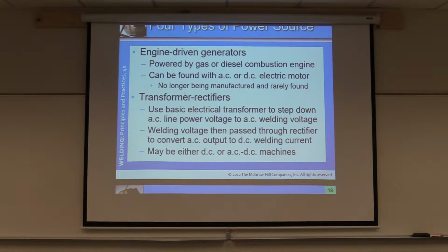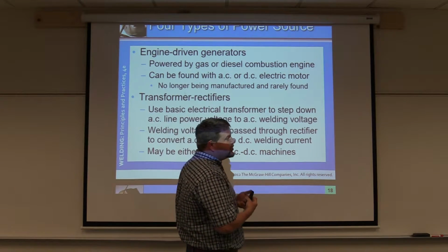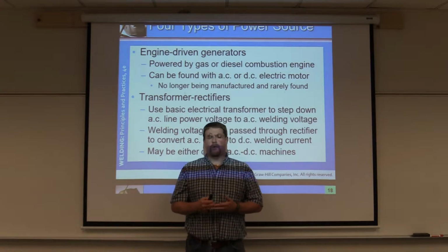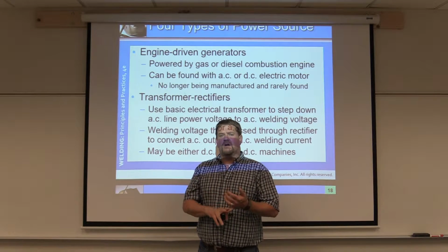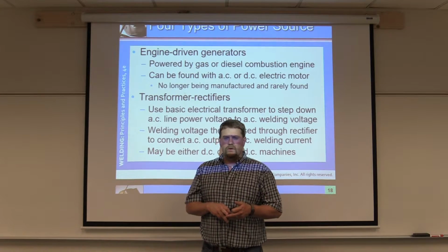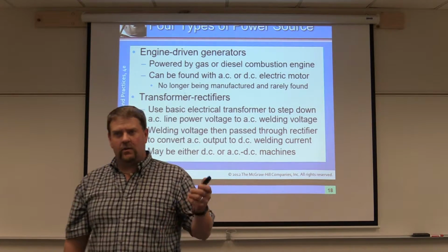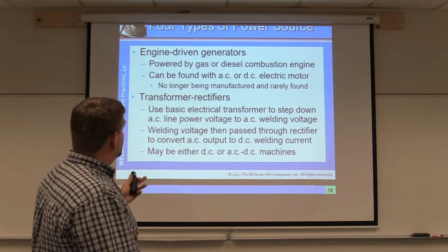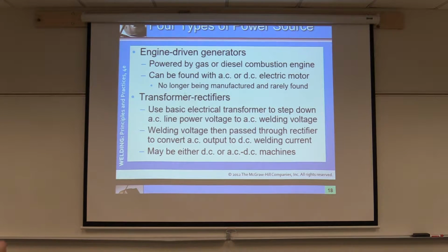All right, engine-driven generators. Basically, the engine-driven generator welding machine type is the one that you would see going up and down the road, most commonly associated with service trucks, equipment, or pipeline welding, and so forth. It's usually the Lincoln or the Miller machines that we see on the back of the truck. It's got its own engine, which in turn turns the generator and produces an electrical charge coming out of it, okay?